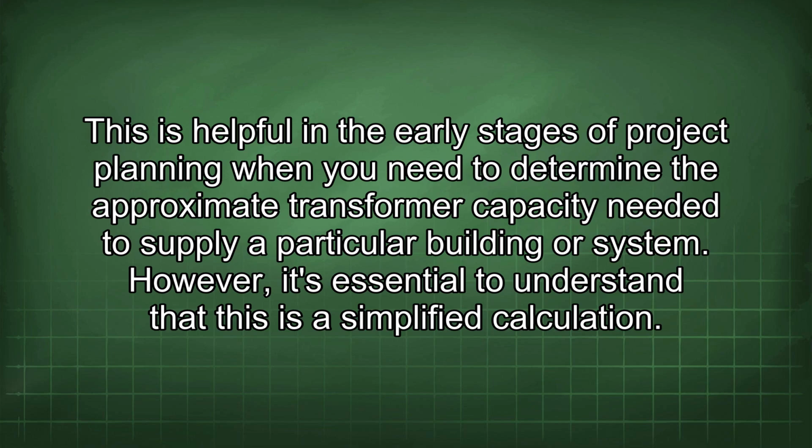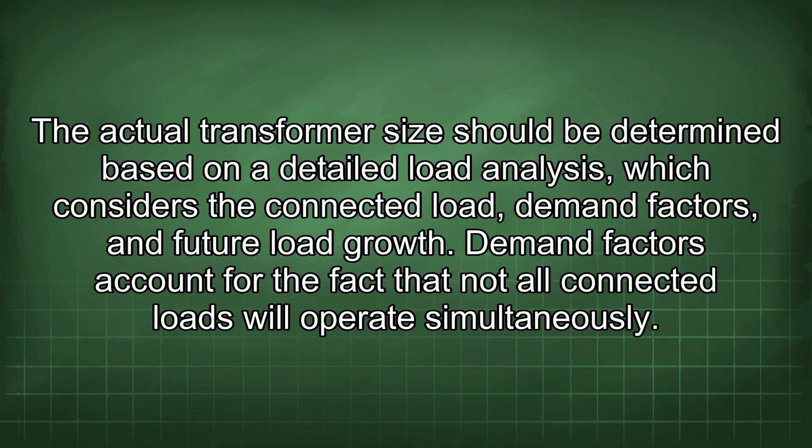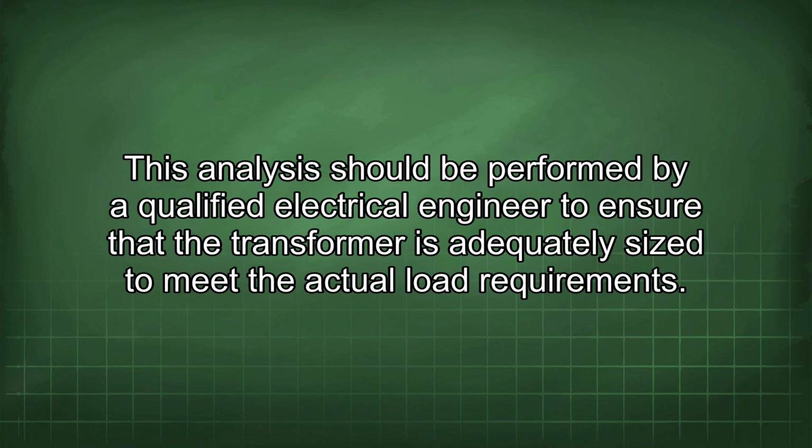However, it's essential to understand that this is a simplified calculation. The actual transformer size should be determined based on a detailed load analysis, which considers the connected load, demand factors, and future load growth. Demand factors account for the fact that not all connected loads will operate simultaneously. This analysis should be performed by a qualified electrical engineer to ensure that the transformer is adequately sized to meet